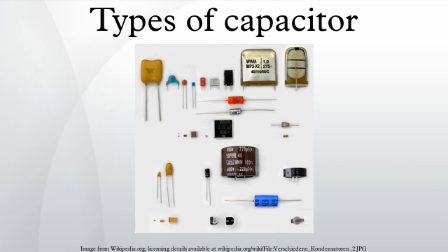Nearly all conventional industrial capacitors, except some special styles such as feed-through capacitors, are constructed as plate capacitors even if their electrodes and the dielectric between are wound or rolled. The capacitance formula for plate capacitors is: the capacitance C increases with the area A of the plates and with the permittivity ε of the dielectric material and decreases with the plate separation distance d. The capacitance is therefore greatest in devices made from materials with a high permittivity, large plate area, and small distance between plates. Theory of electrochemical construction.